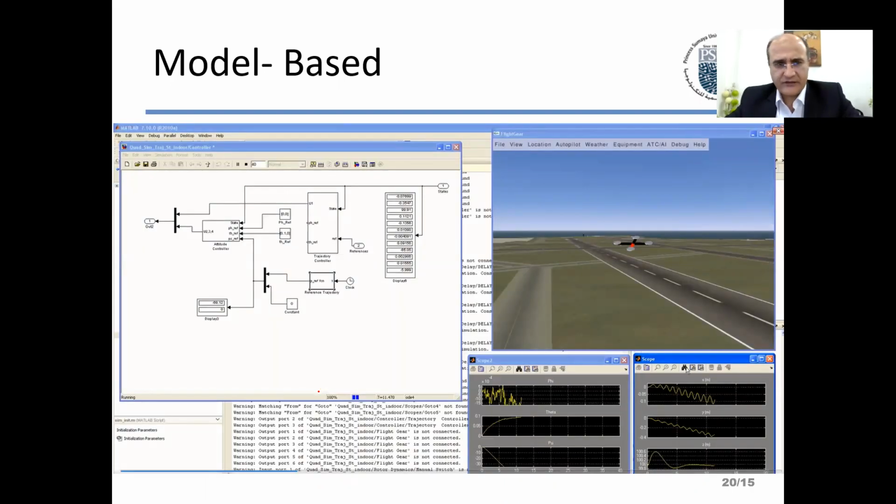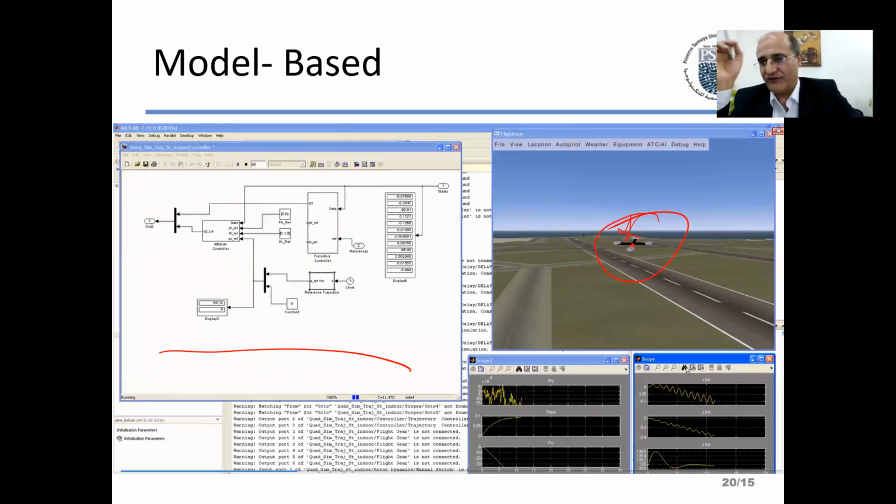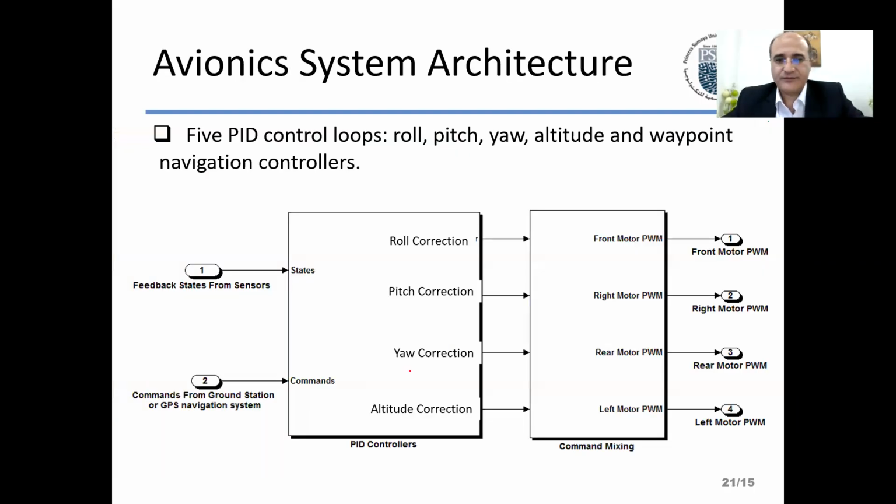Some examples I had from my work with an airplane. This is an airplane. In this one, I'm controlling a quadrotor. This is for visualization only, but I like to put the slide here to show you the gains that I used for the 4 PID controllers for this airplane in this stage. Whoever worked with controllers will understand what I'm talking about. The gains I used here in simulation were the same numbers put on the actual hardware when the drone was flying. I did not have to change a fraction or fine tune anything. This is how much this helps.